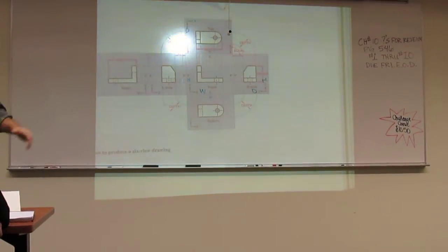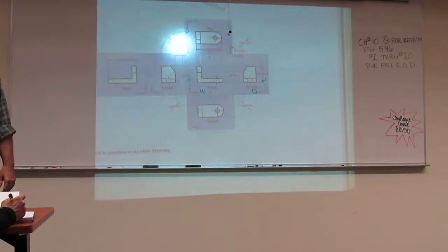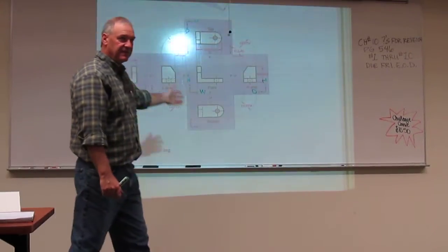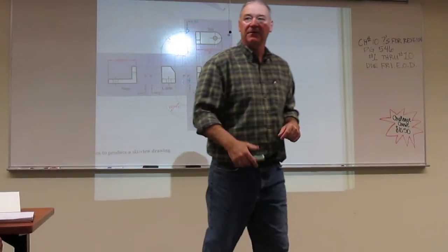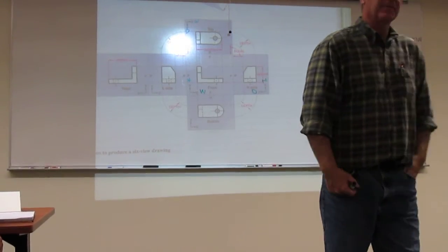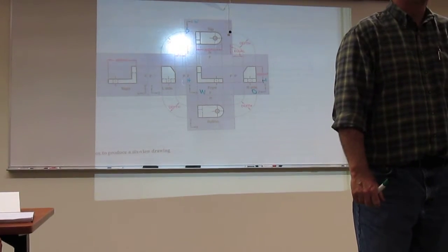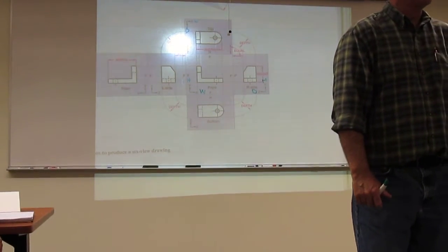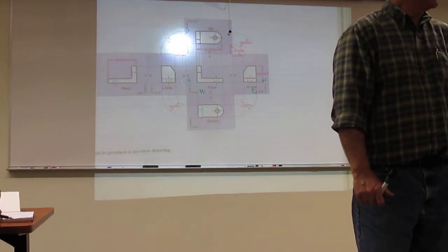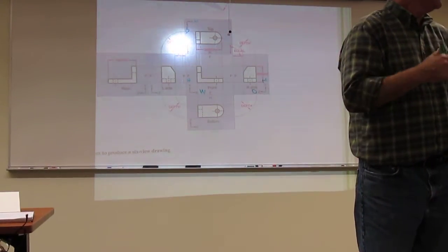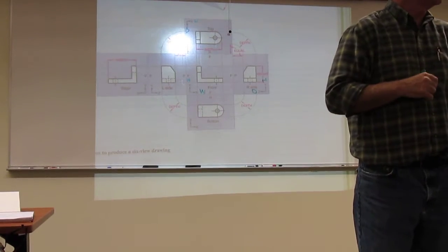Generally, this is what the majority of your objects are going to be: projected as three-view drawings. You will have some that come to 4 or 5 views if they've got stuff in the back of it that you want to display. I've almost never done a 6-view drawing. In fact, I'm trying to search my memory for it. And granted, I'm getting older, but I don't think I have ever done a 6-view drawing, because I have described the object before I get to those 6.